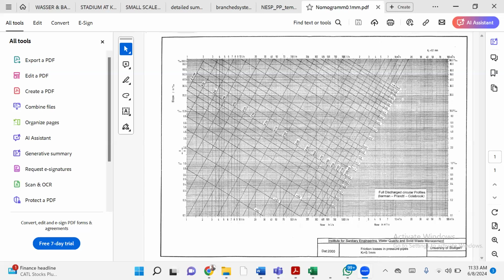So if I'm measuring and I say 2 per kilometer, it means 1,000 meters. So I'm saying 2 over 1,000. I'm losing 2 meters over 1,000 meters. If the value is percentage, it is over 100 meters. We're all engineers, so we know that. So now let's just calculate for those 2 pipes.